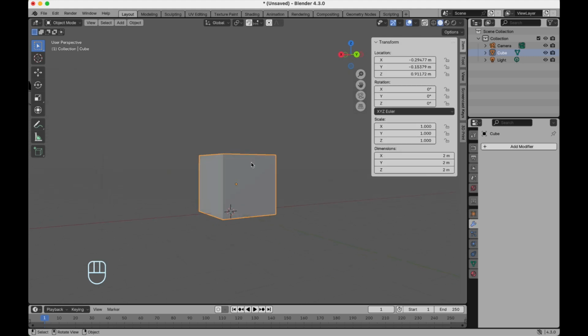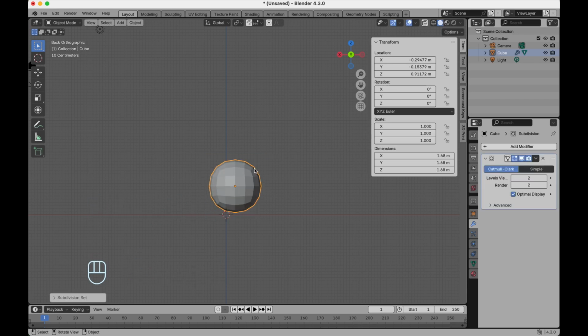We've looked at the basic shapes, and now it's time to begin working with the cube. So, here it is, our cube. We'll be working with it. Let's rotate the cube and position it along the y-axis, so it faces that direction. Select the cube and press Command plus 2. This applies a subdivision surface modifier with 2 levels or subdivisions.